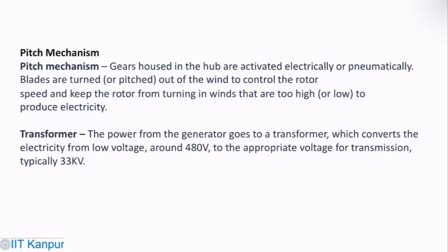You have the pitch mechanism, which basically has the gear housed in the hub and is activated electrically or pneumatically. Blades are turned, or pitched, out of the wind to control the rotor.